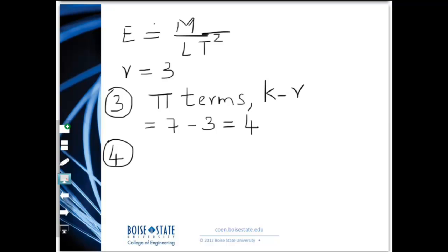So in this case, I'm going to pick L, rho, and mu as my repeating variables. And using this, I'm going to construct the pi terms, in this case 4 pi terms. And again, if you read the chapter in the book, there is no uniqueness to the final solution of the Buckingham theorem. All it says is the number of pi terms should be 4, but somebody might pick D, rho, mu as a combination. That should work because those don't form a dimensionless group by themselves.